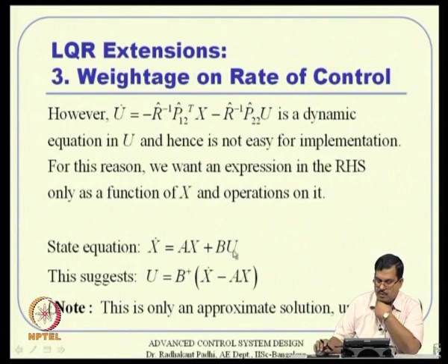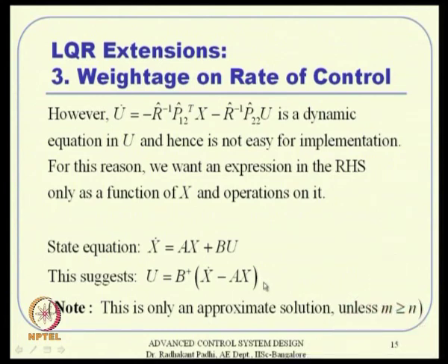We take advantage of this one, the x dot is A x plus B u anyway, we know. So, u turns out to be this solution, where B plus is nothing but the pseudo inverse of B. Remember, this B is not a square matrix in general. So, we cannot talk about B inverse here, and that is where this approximate solution comes in. Anyway, we will not talk too much on that. But then u I can solve from here using this pseudo inverse solution, and because this is an over constrained problem, the pseudo inverse solution is typically not a good solution. That is my own personal comment here. So, do not jump into this idea unless it is badly required.